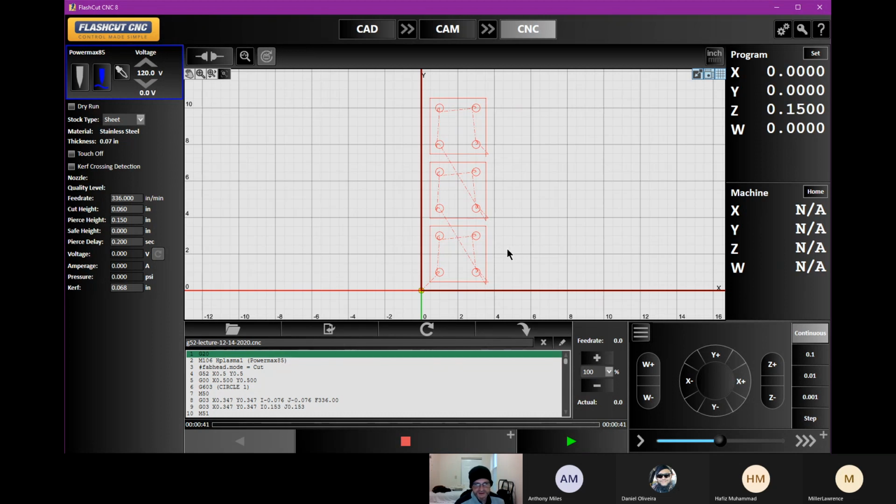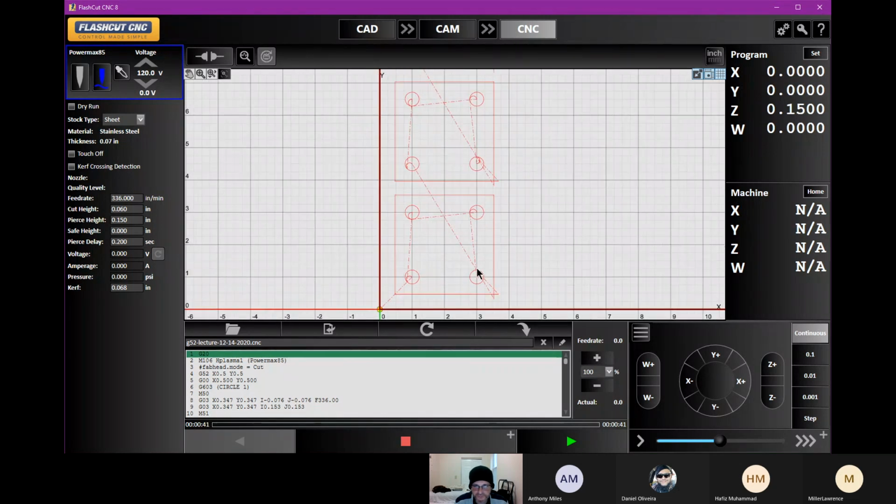Okay, in this instance, our first position, we're going to use Y 0.5, and we got to pick an X position. Okay, that's about a 1/2 inch away from where we started. So we're really close to 3.5. So we'll go with 4. Okay, we're basically flip-flopping it. When we went in the vertical direction, we had X 0.5, Y 4. When we're going in the horizontal, we're going to have X 4, Y 0.5.